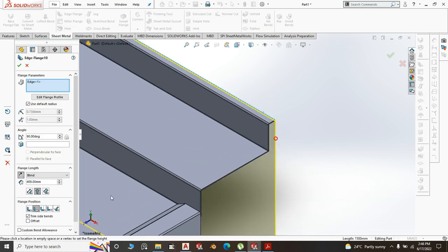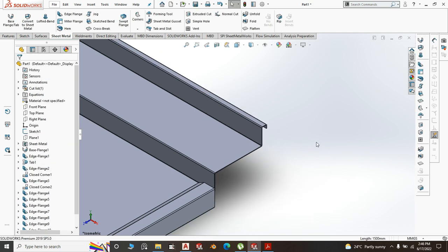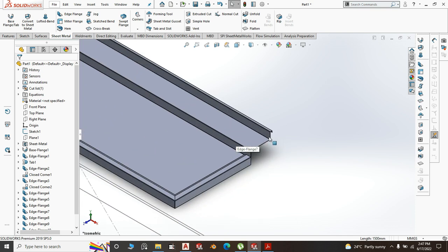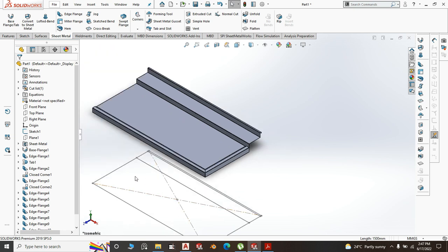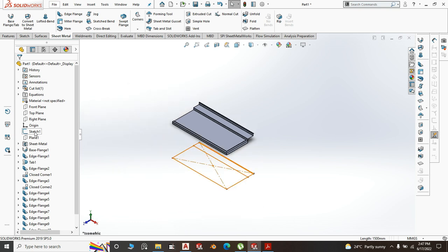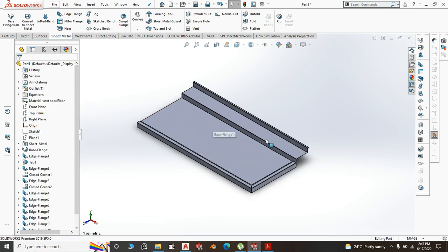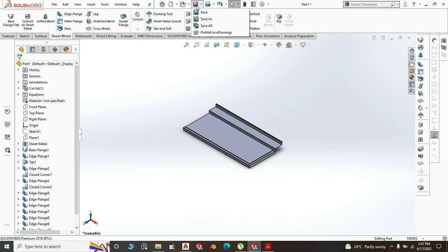In no way will your table be, this is 10mm. In no way will your table be bigger than whatever you wanted, right? Remember, you wanted a table of 1500 by 750. So if you do that sketch of the overall dimensions, then you give your edges, the sketch of the edges, you give them relationship basing them on the initial sketch. It's not gonna be big, right? The size will remain the same, and I feel like our top is good, so we can go ahead and